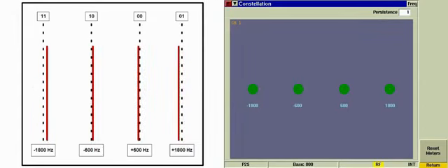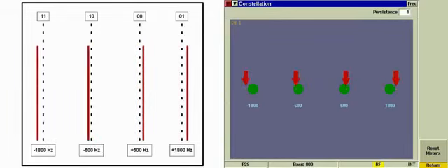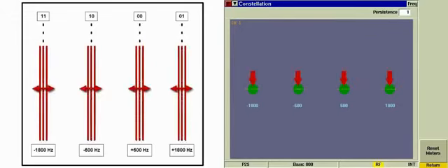In this example, the signal has a low symbol deviation but acceptable RMS deviation error. The deviation points are narrow, but do not line up well with the target deviations. In this example, the signal has a high symbol deviation but acceptable RMS deviation error. The symbol deviation of this signal may measure within limits, but the RMS deviation error is quite high.